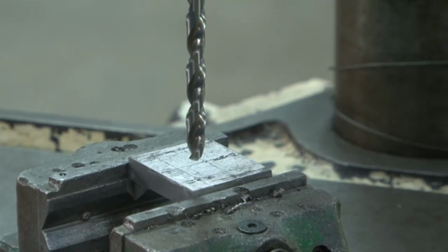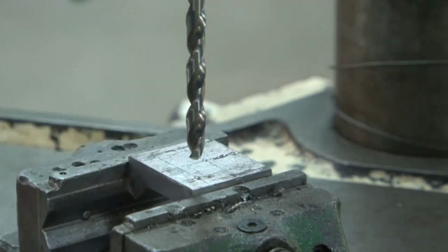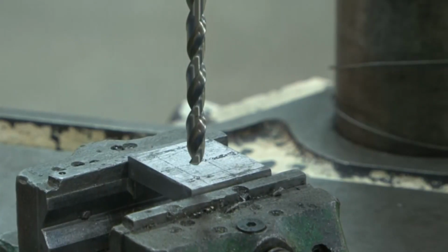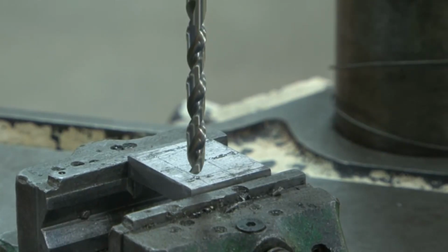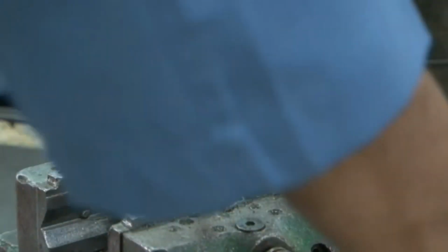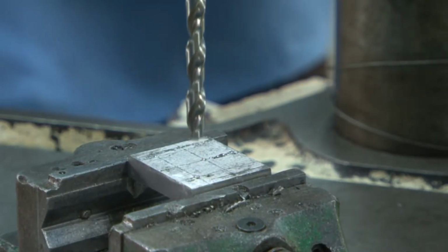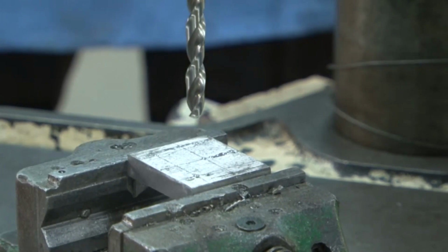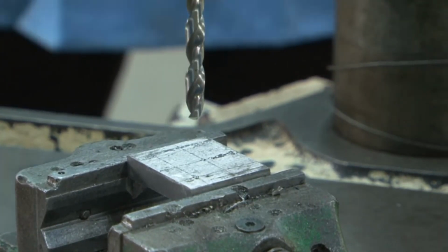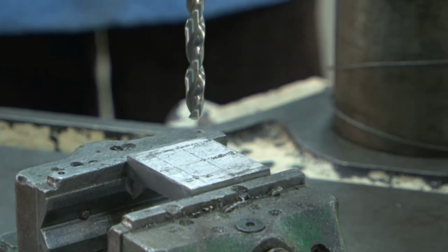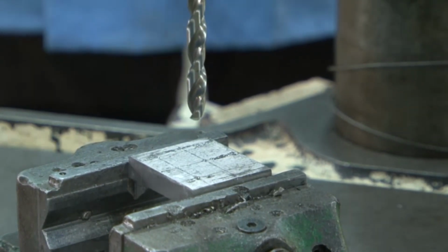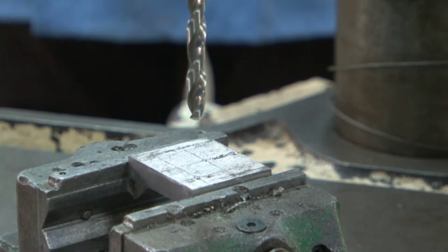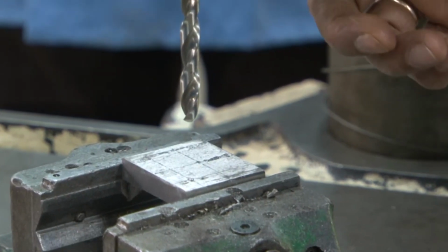Well, first of all, the job has to be mounted for drilling the hole. So, the job has been mounted using the vise, and according to the drawing, the hole that has to be drilled is a tapped hole of 10 millimeter diameter. If you remember, as I was telling you, when the hole is drilled, the drill diameter has to be less than the diameter of the hole, because if you take a 10 millimeter drill to make a hole of 10 millimeter, invariably the hole diameter will be a little more than 10 millimeter, and you cannot meet the accuracy. Therefore, the drill that has been selected here is an 8.5 millimeter drill.